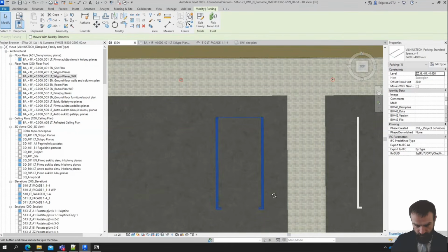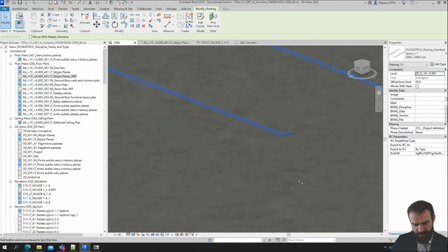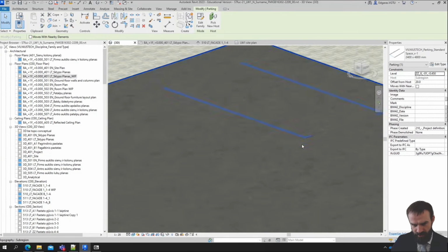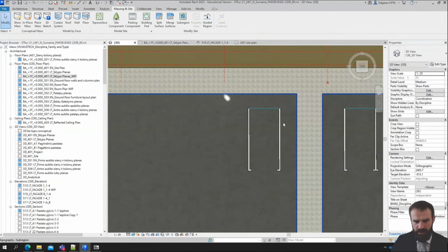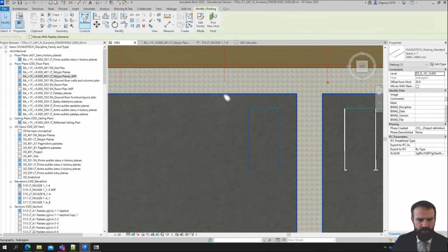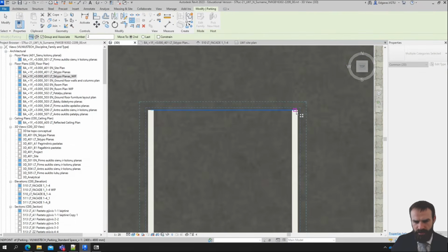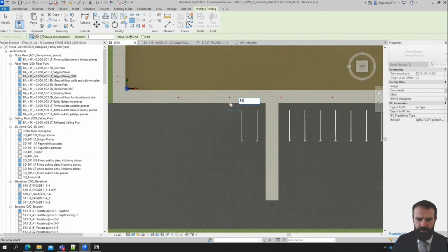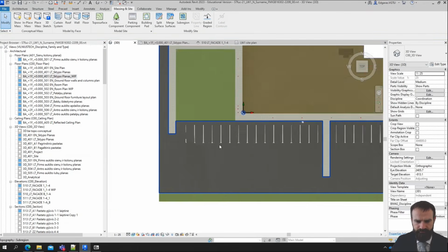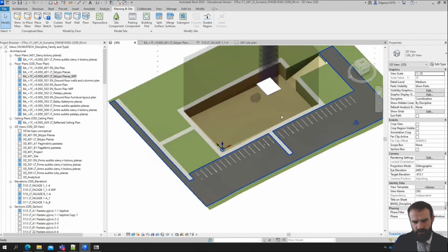So in the 3D model, it can look strange because it will be lifted or hanging in the air. In 2D drawings, it will look okay because I'm looking at the 2D presentation of my project, and from the top it looks okay. I just use the array tool and snap and write 15 places for my car parking.